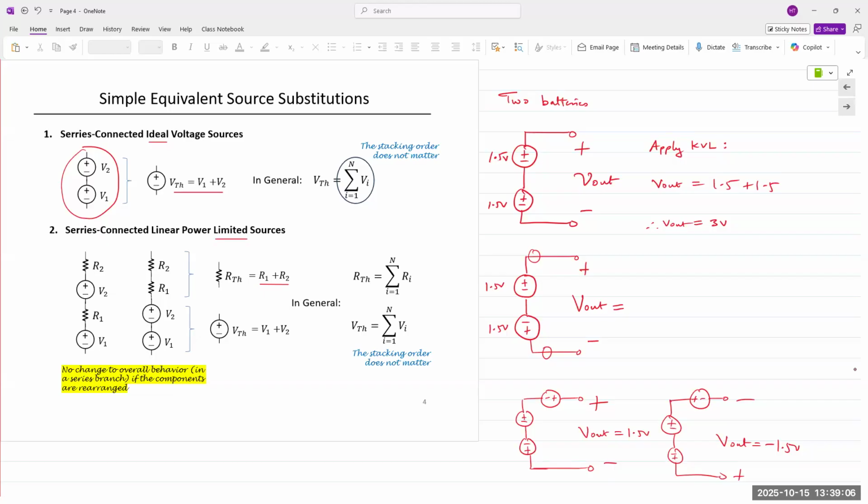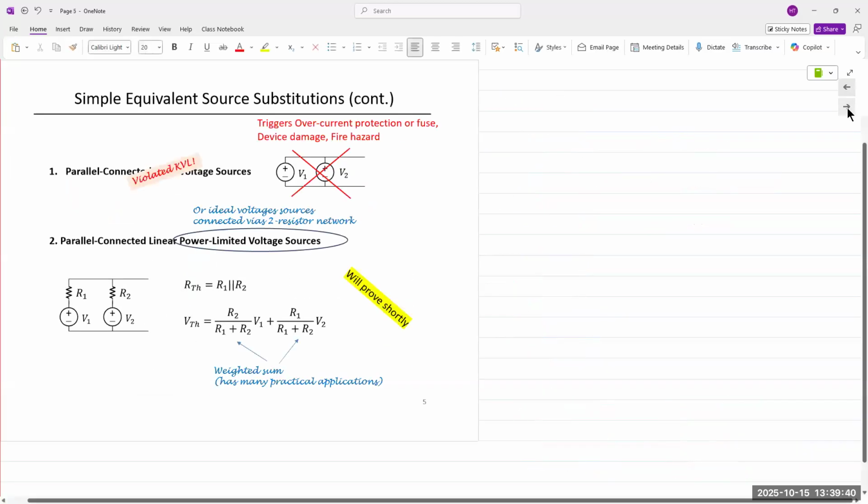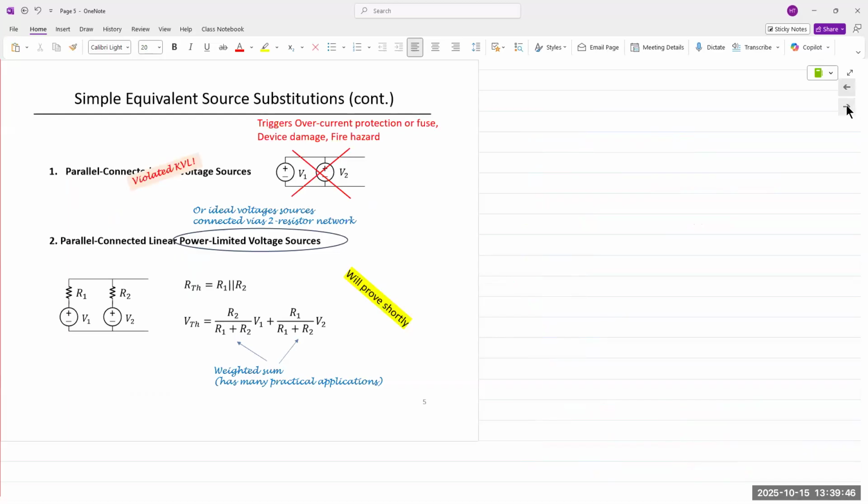So if you wish to perform an experiment, take 4 batteries together and see if you can measure the resistance of these 4 batteries connected in series, because that would give us sufficient resistance. Okay. So RTH for series connection is simply summing up all the resistances in series, and then VTH, the Thevenin voltage, is simply summing up all the voltage sources in series. So straightforward as far as equations or analysis goes.